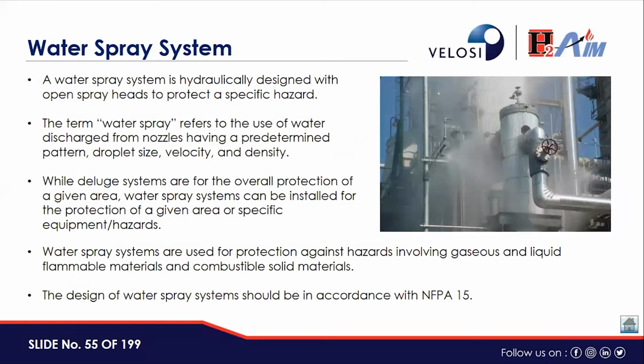Then water spray system. Basically, this water spray system is hydraulically designed with open spray heads to protect a specific hazard. The term water spray refers to the use of water discharged from nozzles having a predetermined pattern, droplet size, velocity, and density.